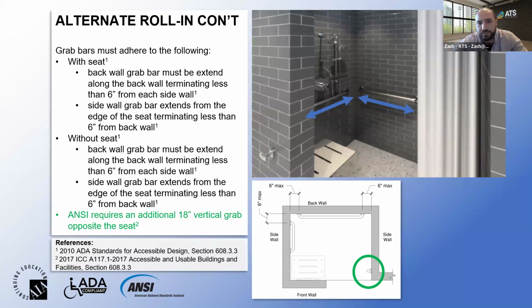Additionally, the shower space should not be less than 1,500 millimeters wide and 900 millimeters deep. So again, you can get the design guides based on various provinces and the ADA design guide as well, which will cover all this in great detail. But we'll certainly be sending out the copy of the presentation as well.